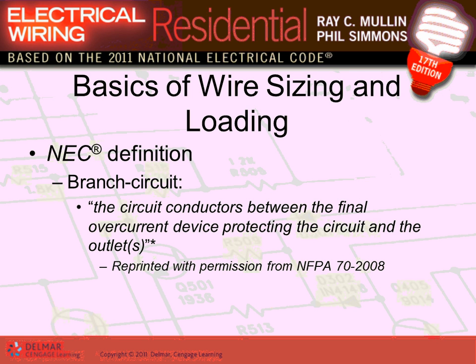Now we brought the power to this panel. The third circuit is called branch circuits, and the name is very important if you guys want to stay in this business. Branch circuit is the wires between this circuit breaker and the utilization equipment, as in lights, receptacle outlets, AC. These are called branch circuits.